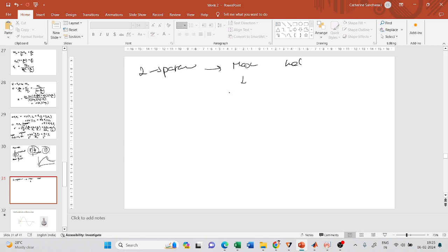So each element has one parameter, a spring and a dashpot. Each had one parameter, so it is a two parameter model. In the same way, a Burgers model is a four parameter model because it had four elements and correspondingly four parameters. Similarly, I can have three parameter models also.